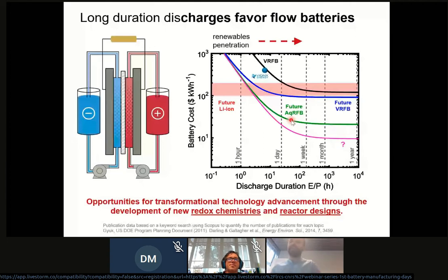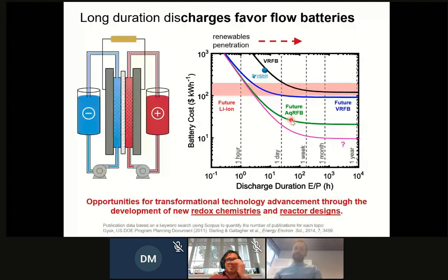So there are a lot of approaches these days on looking at flow batteries, and the basic premise is that they are very interesting because you can decouple the energy from the power, okay? And that is something that you cannot do with lithium-ion battery because you have a sealed compartment. But here, because you have flowing electrolyte, you could actually get higher energy just by increasing the volume or the concentration of your electrolyte. But you could also make higher power if you increase the area of your reactor. So you can play with these two, and that is something that is very interesting for the grid because you can make modular units. The problem with flow batteries is that they are currently too expensive, okay?